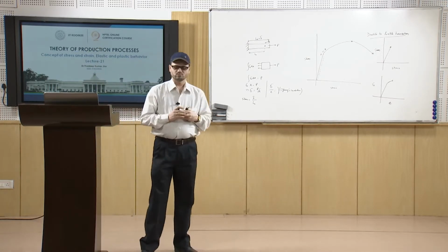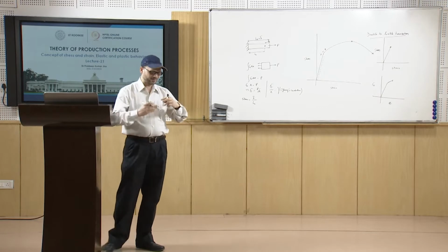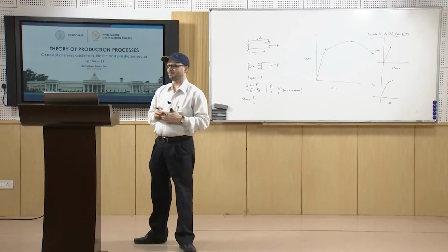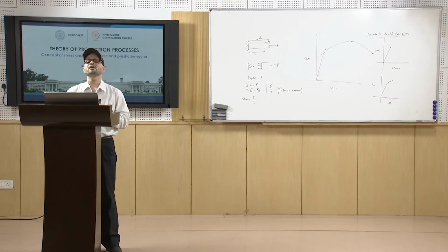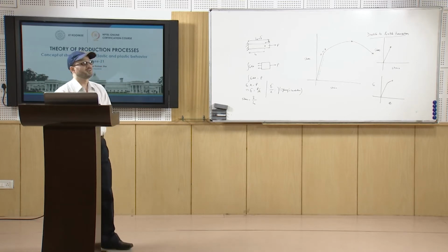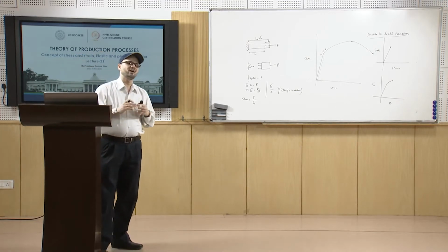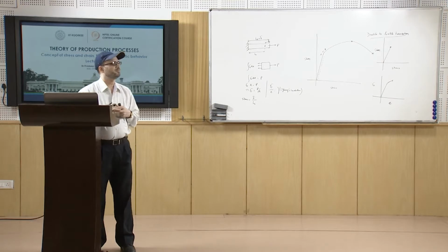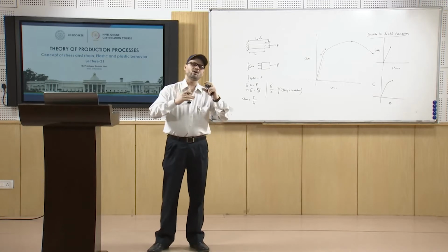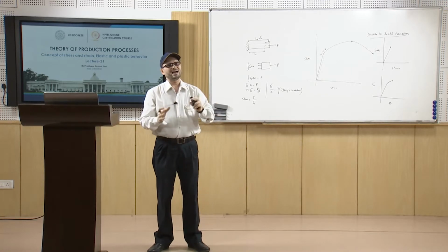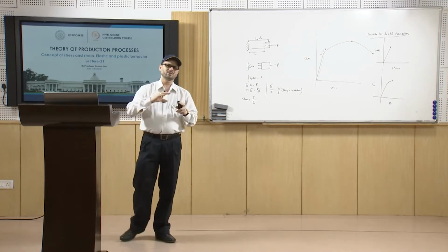is subjected. Now, we will discuss why failure occurs. So, what are the conditions which constitute the failure of a material? Now, the failure may be because of excessive elastic deformation, or yielding, or excessive plastic deformation, or it may be because of fracture. So, if you look at deformation or failure, it has only 3 modes: either excessive elastic deformation, or excessive plastic deformation, or fracture.